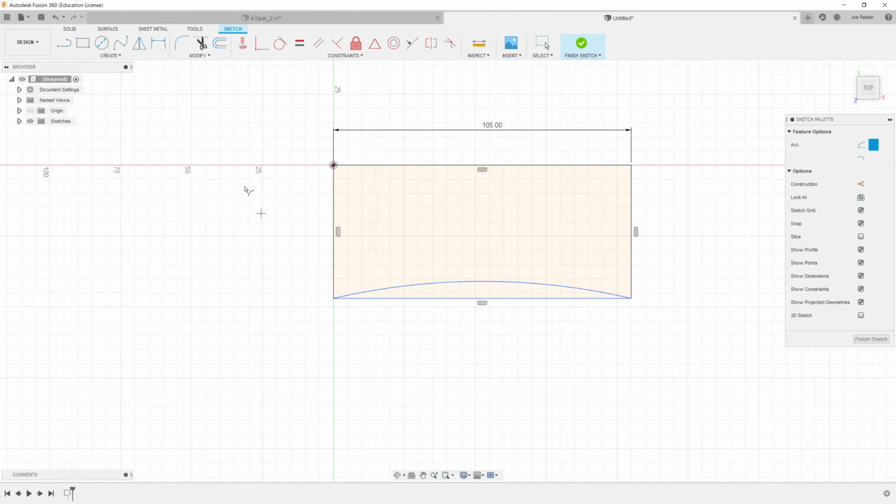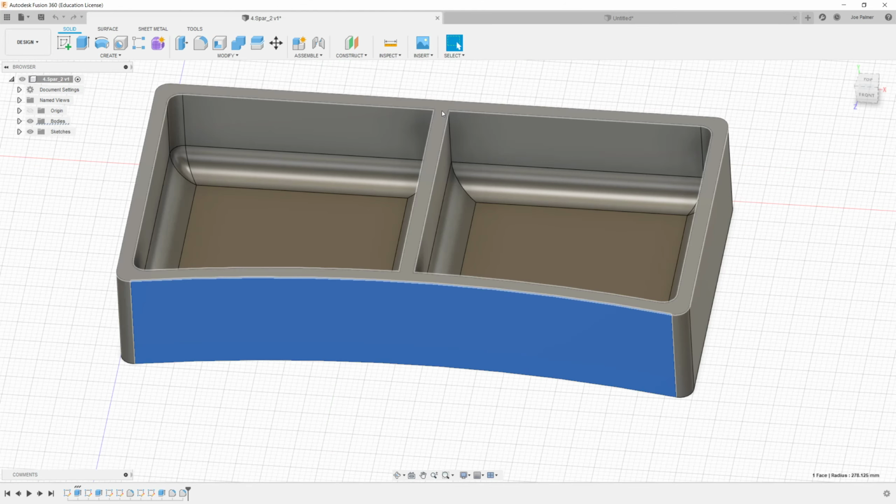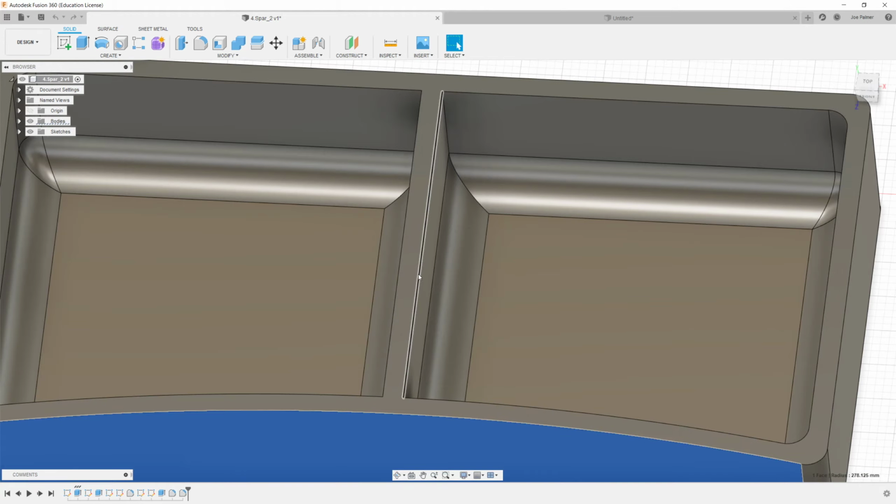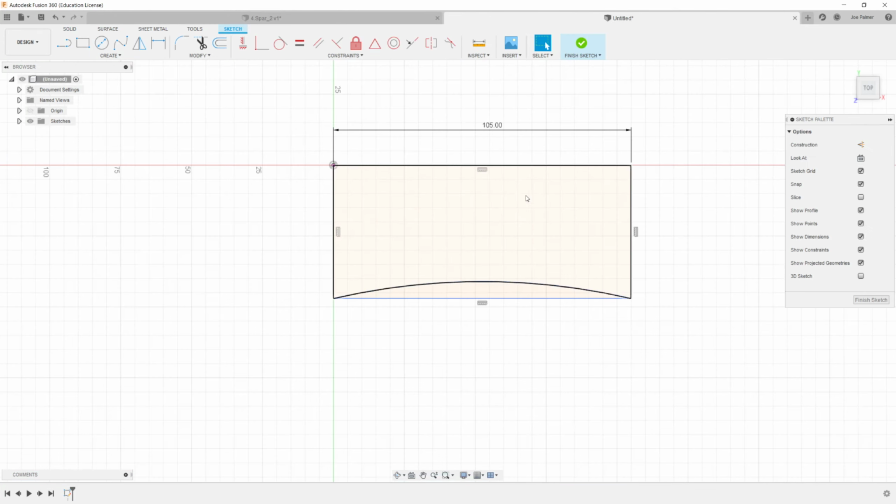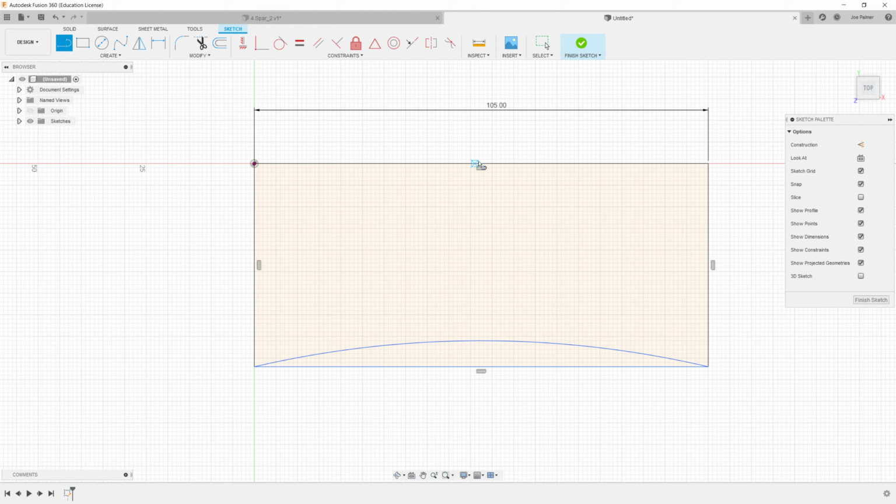Okay, I can also see from my reference component that I have a rib or a web of material running down the center of the component. So I'm going to sketch this in as well. I go back to my sketch window and get my line tool. If I start sketching from the top of my component, once I get towards the center of a line, you'll find that it snaps to that midpoint, and we get an indicator of that by seeing this blue triangle here. So I'm going to snap to the center of that top line.